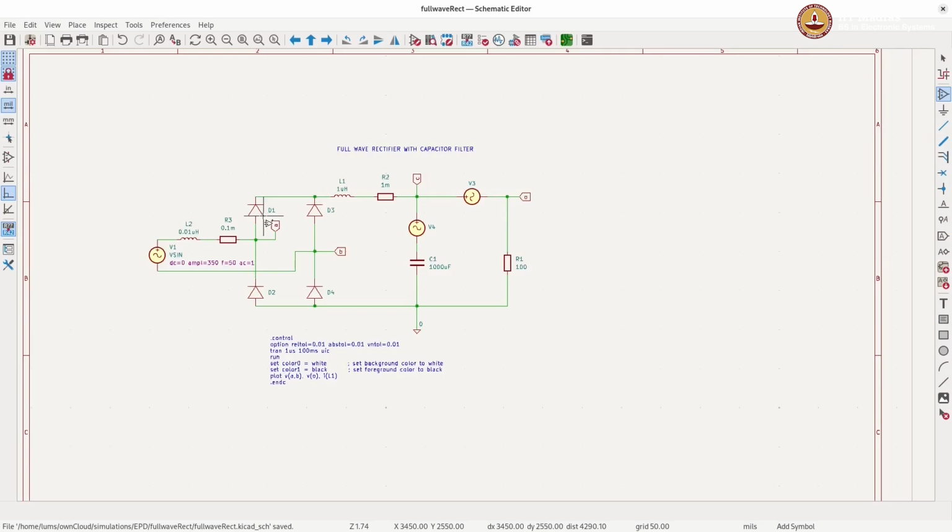So this way it will ease a lot of your burden when you are doing future circuits. But as you go along, you may have to work once on each customized component in order to make it proper and behave proper. And once you do that, it is available to you for all your future simulations. So this is an example of how you would make a custom diode.